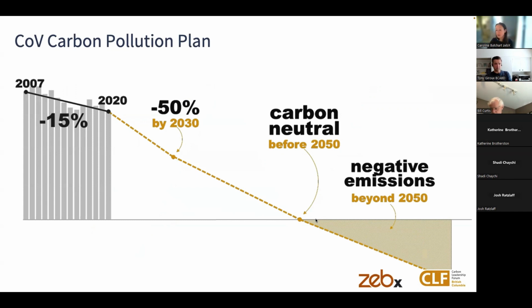So for Part 3 buildings starting in September this year, any new building going through the building permitting process must submit the embodied carbon associated with that building. There are no targets just yet. Targets will start in 2025. At the moment, they just want you to calculate the embodied carbon and submit that with your building permit application.